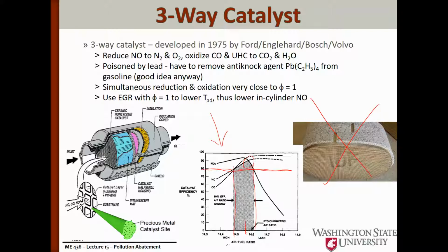There is another way to minimize the NO and CO formation, and that was to use exhaust gas recirculation to avoid the high temperatures where things go to equilibrium, and run at a lower flame temperature. So we're still stoichiometric, but we've lowered the flame temperature because you've diluted it with products. So that was an approach taken by the Japanese.